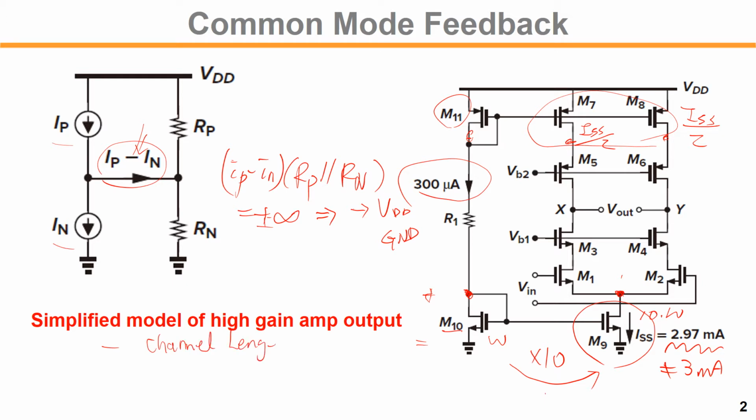So the first reason is the channel length modulation effect. You know that the current mirror error coming from channel length modulation, meaning different VDS, right? Now second, the VTH variation or mismatch. The device mismatch will result in the current error, right?